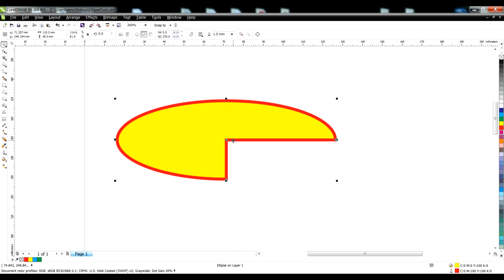And if we want to see only half of the ellipse and not the whole ellipse, or if we don't want to miss only 1/4 of the ellipse, I insert in this window by double clicking with my mouse key and input 180 degrees. And if I click enter, in that case I have only half of the ellipse. I will click undo of this command, so I will get the previous shape of the ellipse.